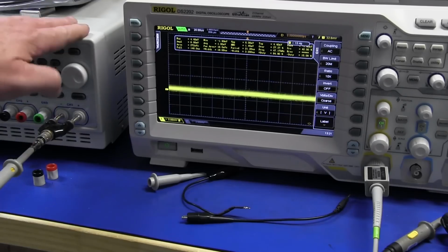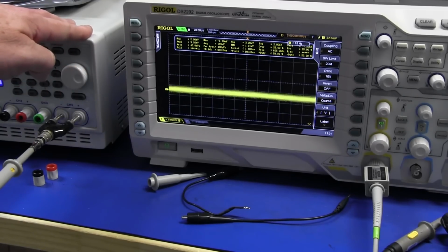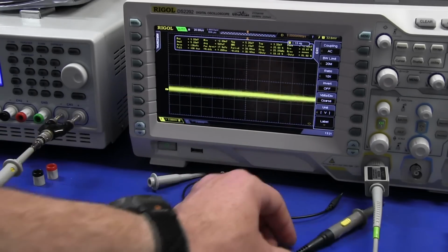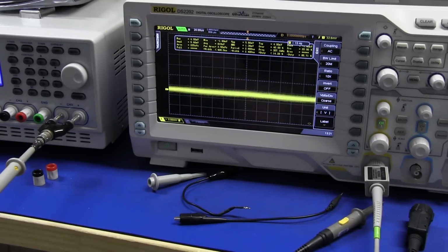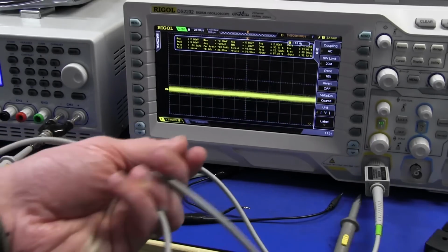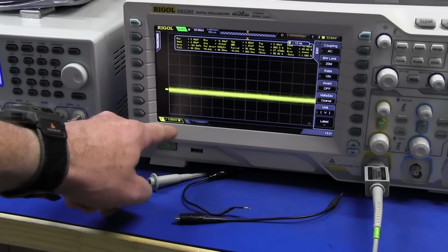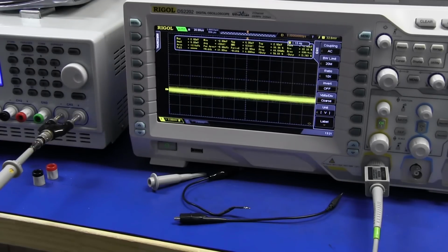So really, because the bandwidth of this power supply is specified from 0 to 20 megahertz, we can't just use our scope probe on ×1, because for this probe that's only giving us an 8 megahertz bandwidth. So we have to put up with the fact that we're using a ×10 probe, and here's an Agilent one. This is my 500 megahertz high quality Agilent probe, and we can only go down to 5 millivolts per division because of the ×10, but there you go.